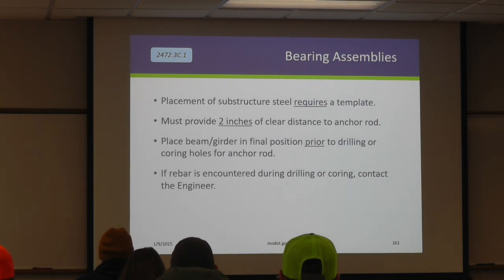Because we're doing this post concrete placement, we have to make sure that we have at least 2 inches of clear distance between that anchor rod and the reinforcement that's been embedded in that substructure. Again, that number 11 bar is that big for a reason. We don't want to shave the steel off of it. So they should have provided a template.